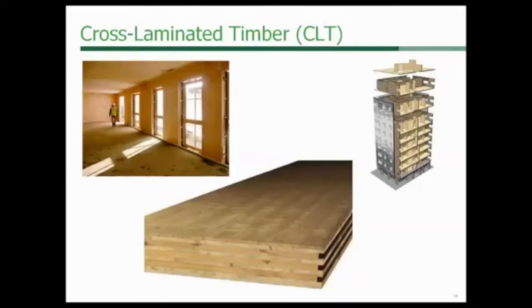As you can tell, it has high structural capacity, a great leap in structural capacity compared to light frame construction. It also has high fire resistance given that it's solid wood. There's no concealed spaces between repetitive members in the walls or in the floors. So the combination of high structural capacity and high fire resistance make it a candidate for all kinds of buildings that before now it didn't make a lot of sense to have out of wood, but now it does.